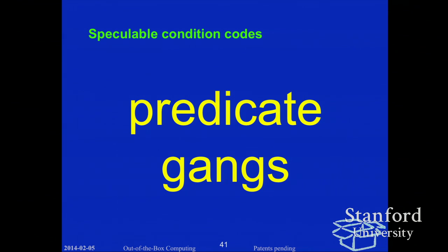The problem is that this is a global state. It's real nice. You can do a subtract and get the subtract result, and in addition, immediately branch on whether you'd gotten to 0, for example. The condition codes were designed to support decremental looping. But the next operation that comes along that uses the condition codes just clobbered your condition codes.